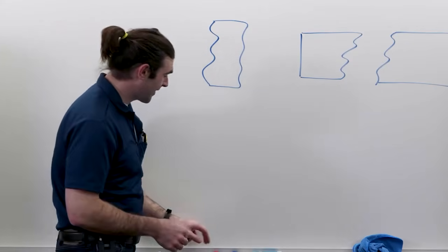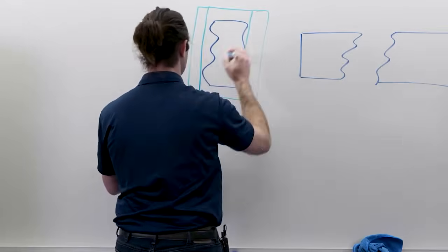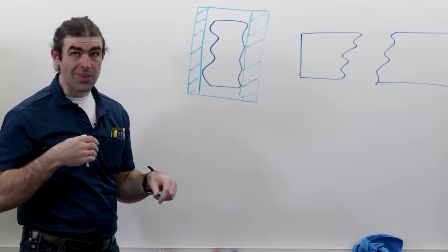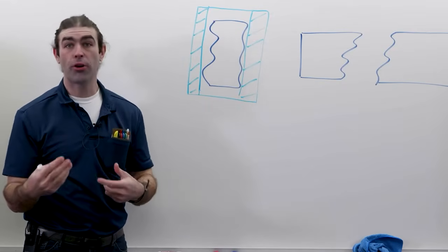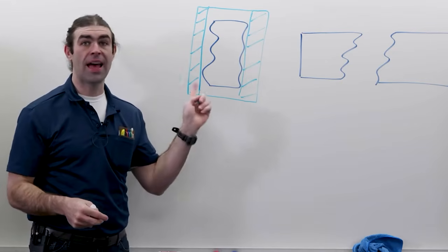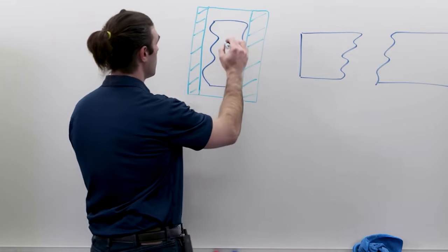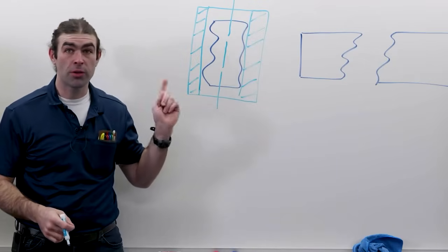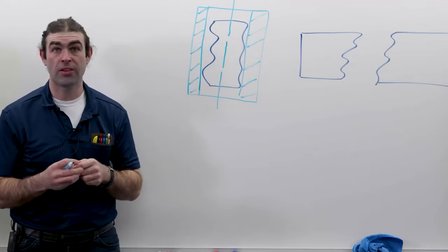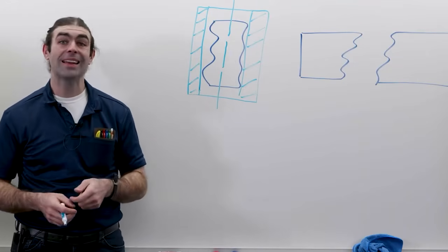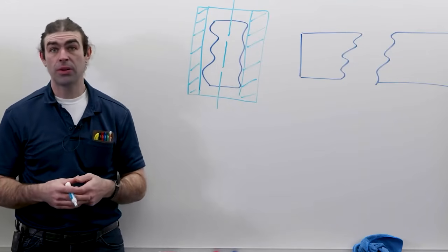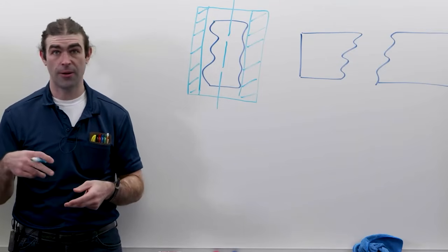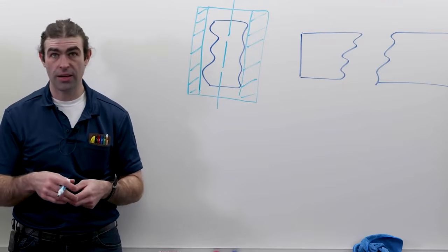You would end up with a cylinder that collapses on that part, and the axis of that perfect cylinder becomes the axis of this feature, right? That would be the axis we would use to figure out if the perpendicularity tolerance is within tolerance. As a practical method, this can be simulated with a collet or a ring gauge or all kinds of things, or even just running an indicator over it.